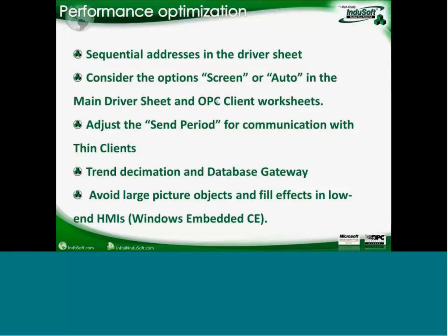In the main driver sheets or on the OPC driver sheets, there is a column for scan, and you can select the option screen or auto for tags that you only use to display on the screen. Do not use it for alarms, for history, for reports, for anything else. So we automatically enable the communication when the tag is being visualized, and disable the communication when the tag is not being visualized